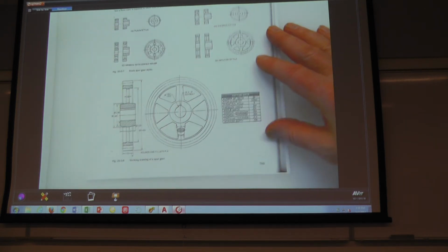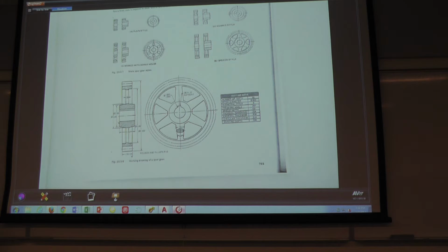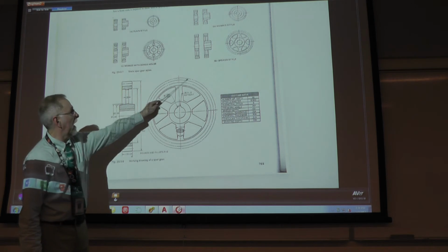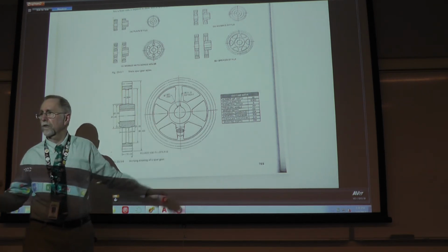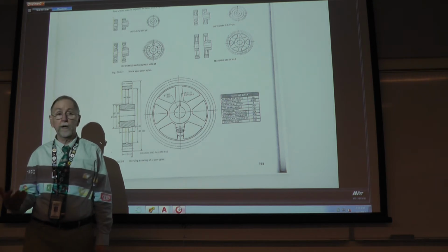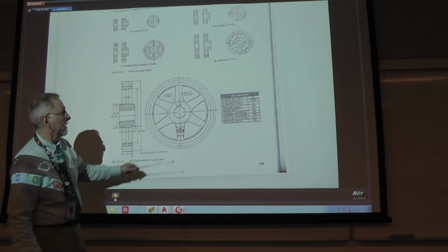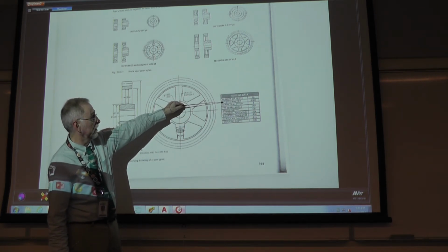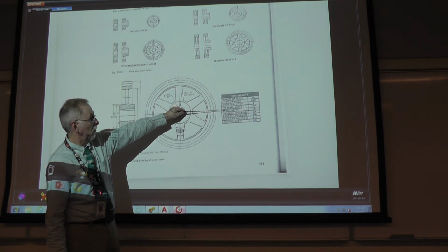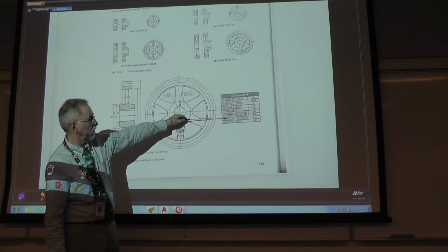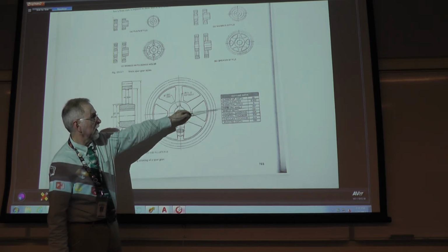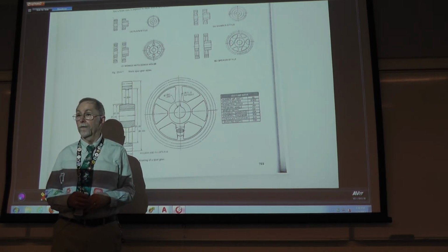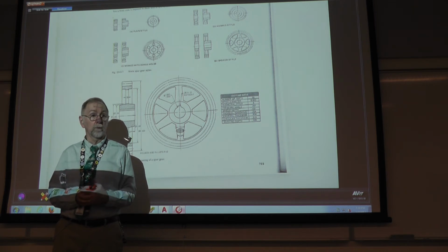If the front view is included, which in your particular assignment is not going to be included, we're just going to do a section view in here. The outside diameter and the pitch diameter and circular pitch a lot of times are just shown as a phantom type line or a hidden line. And what's included is the cutting data, which could include the number of teeth, the pitch diameter, diametral pitch, pressure angle, hole depth, chordal addendum, chordal thickness, circular thickness, and working depth. That's all the information that a machinist would need to go get his cutters, or her cutters, as the case may be, and cut the tooth form correctly.